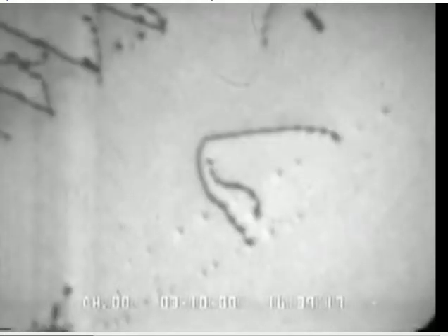So the thing is, when the atoms move within an actual system, that sort of coordinated movement which we saw in the last video is not usually observed. Rather, this kind of movement of the dislocation is observed more commonly in materials. As you can see here, this is a dislocation which is pinned within a system because of the different precipitates which are formed within a crystal.